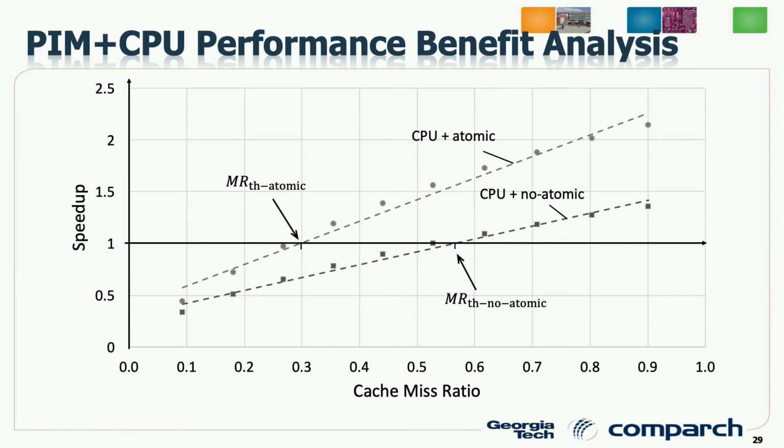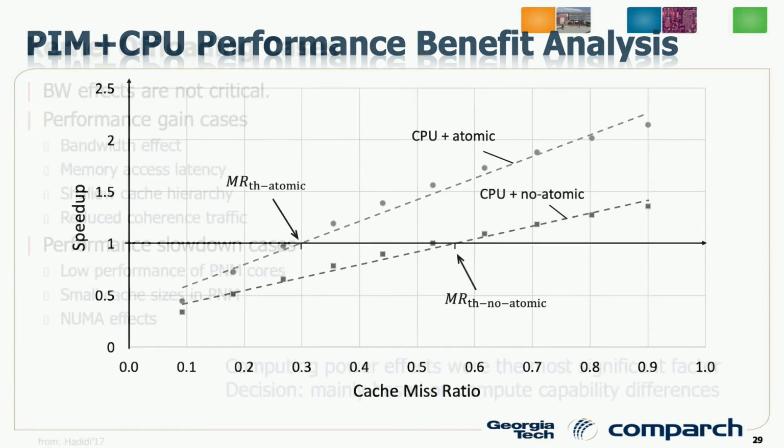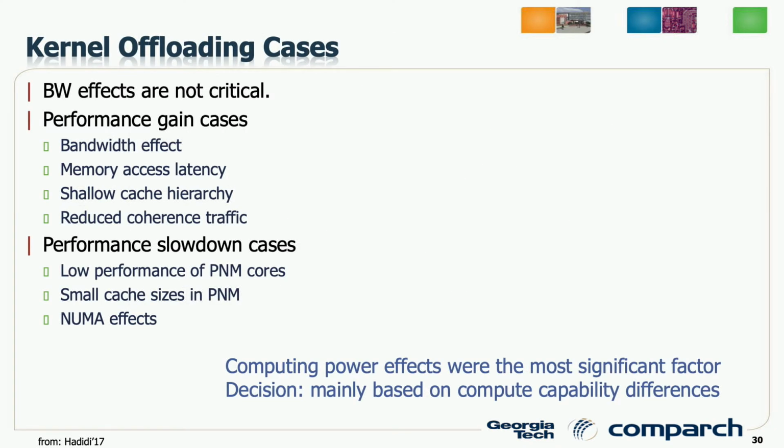And so the PIM was just offloading one single instruction. But the PIM programming models have various spectrums. We can offload just a single instruction, or we can offload entire kernels. Entire kernel means we are assuming that the processing memory has an entire core sitting just next to this memory.